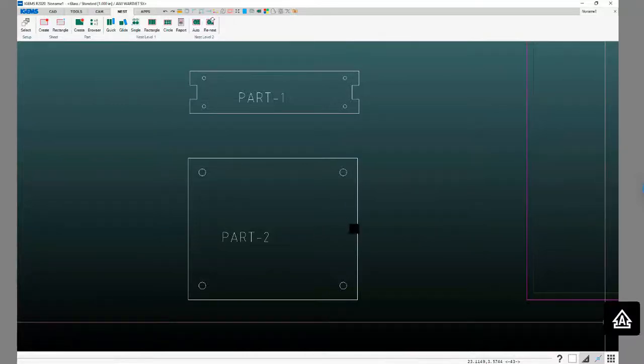Hey Dan, in case you haven't figured it out, when you know you're going to do common line cutting, you don't want to add your toolpath to the outside of the part. You can add your lead-ins on the inside of the part, but you want to leave the outside cuts to be done with the common cut command.